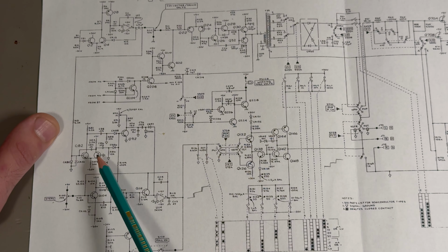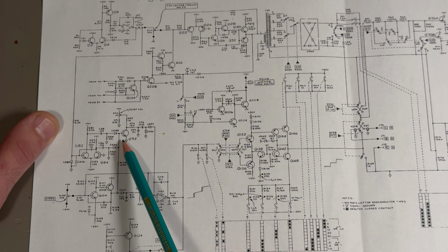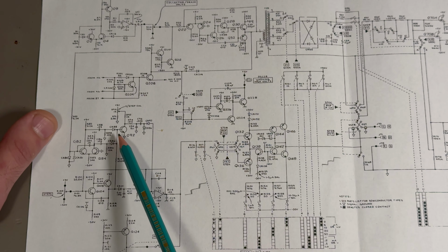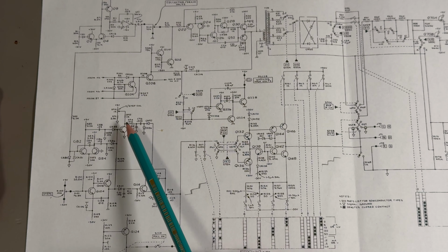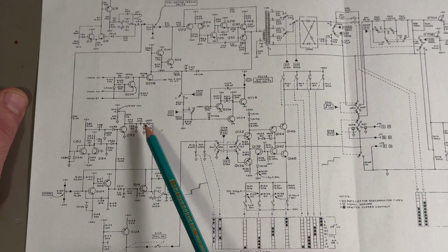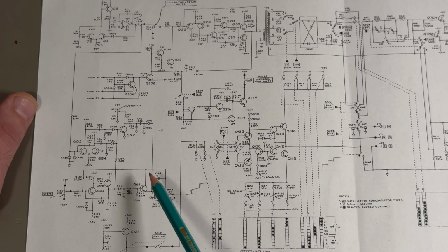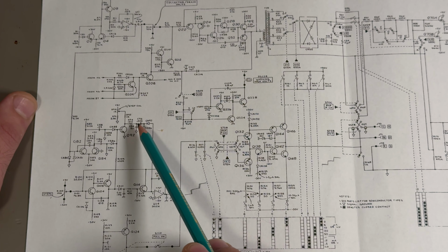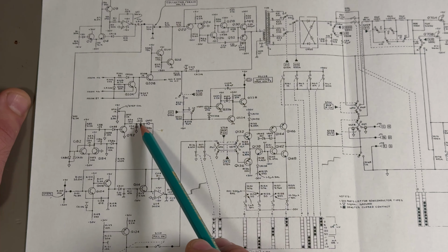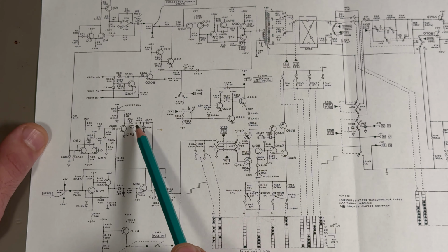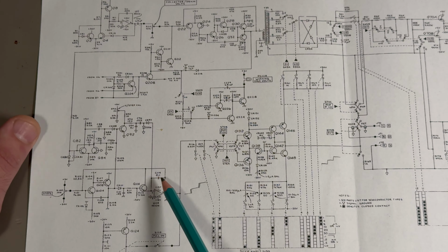So a comparator, both of the collectors are sensed and ORed through diodes. They turn on this transistor every zero crossing, which pulls this node low every zero crossing and pulls some charge out of this integrator. This charge is always the same because it's basically the amount of charge that was stored on this capacitor here. So you can see that's a 22 nanofarad and the integrator capacitor is 100 nanofarad.